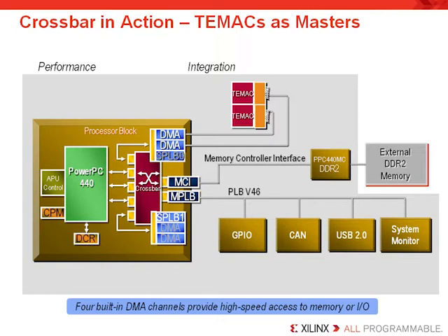Sounds like maybe the TEMACs should have been connected to different DMA ports so that the special arbitration would not be necessary. Recall that there is a separate unused multiplexer at the bottom of this diagram. If we'd taken one of those and connected down there, we wouldn't have to worry about that. The TEMACs are connected to the processor block through a thin wrapper that is provided with the embedded development tools and attached to the DMA port.